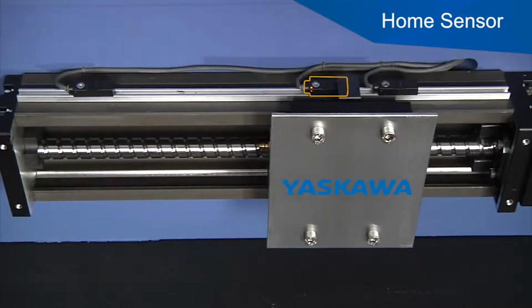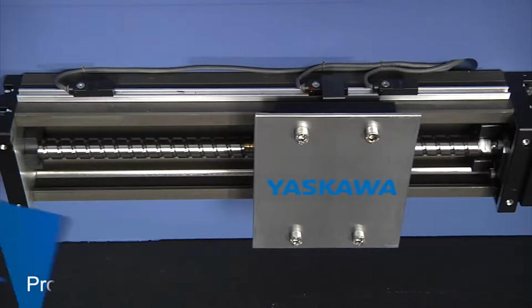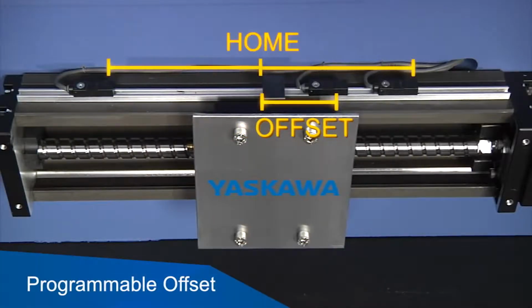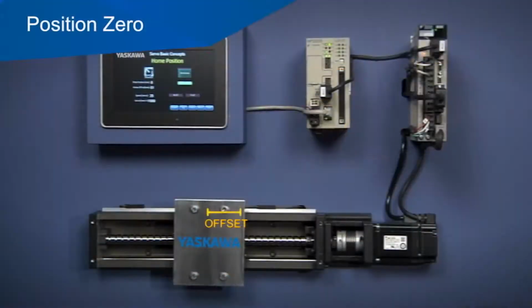We could use this sensor as the home position, but if we did, we'd need to physically move the sensor to calibrate the system. Instead, the axis moves a programmable offset distance to stop at a home position. Our final stopping point is then defined as position 0 for the controller's coordinate positioning system.